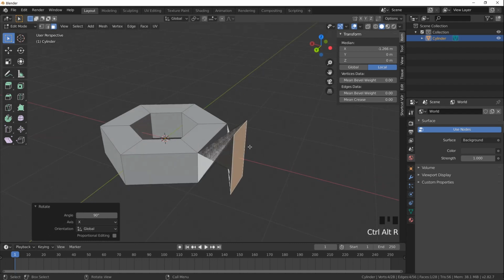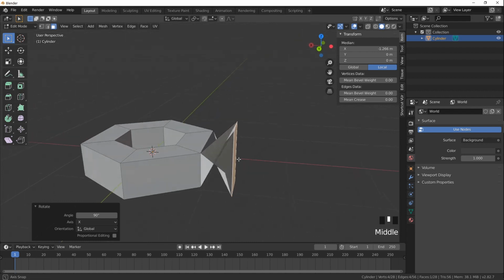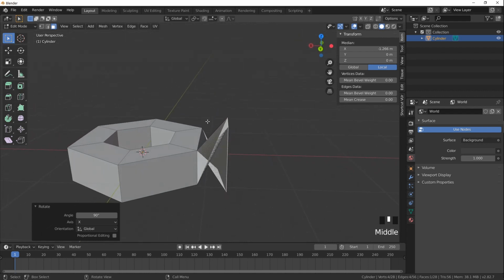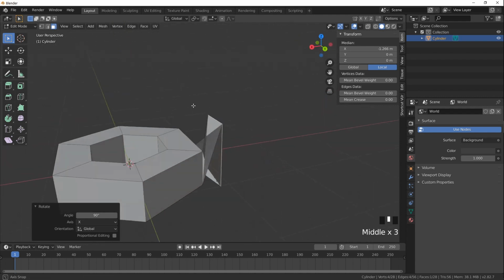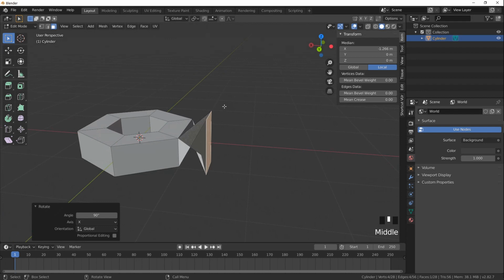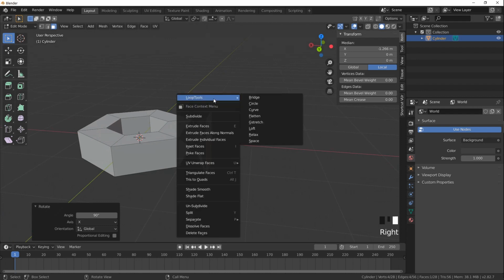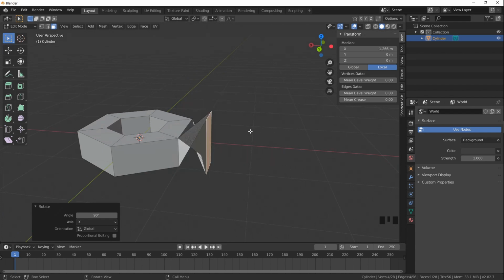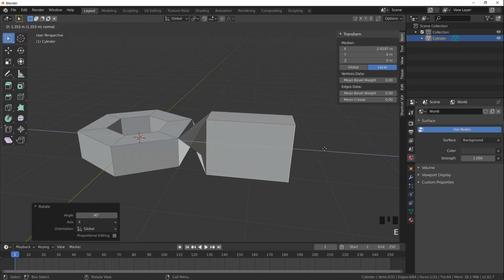Now I want to repeat the same operation that we have used before, but this time, instead of using the active tool, I want to show you what are the shortcuts. And usually most of the time I use the shortcut because they are quite faster. So let's say that starting from this face I want to extrude it. Don't worry if you see this bad result here, it's gonna be fixed later. So now with this face selected, I can just extrude directly. If you press right button of the mouse, you see that you can extrude faces just pressing E. So if I press the E key, I can extrude this face, for example, of 1.5.